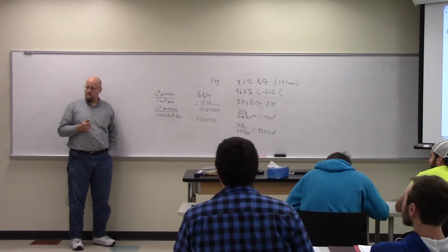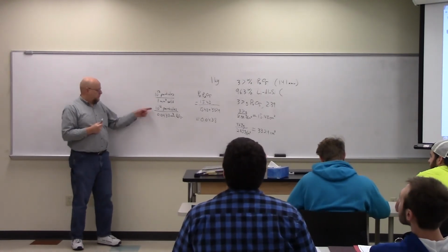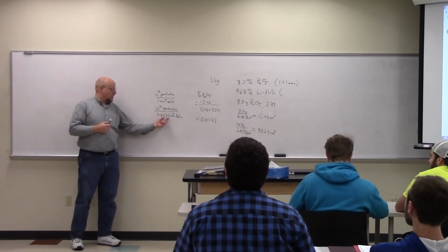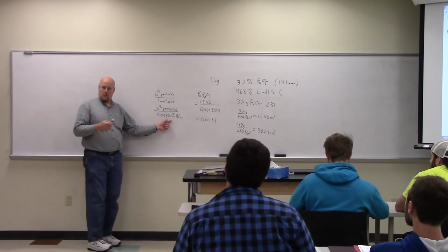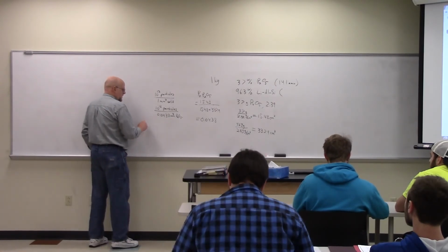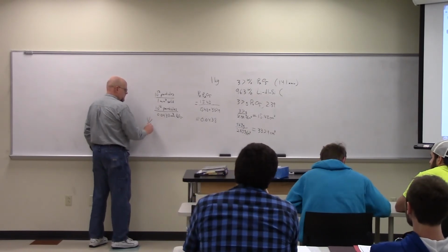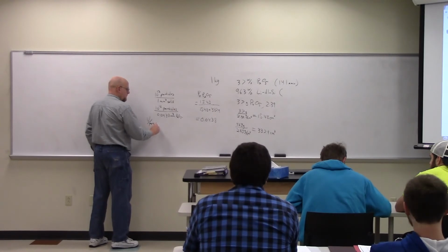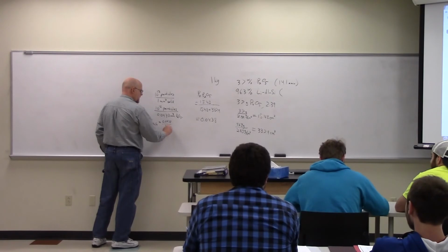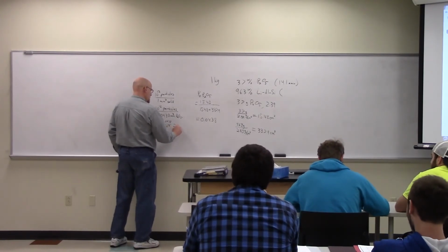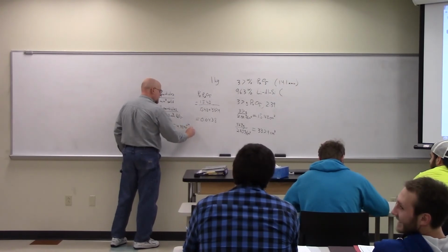That make sense? So that 10 to the 12 particles is distributed evenly among 0.0438 cubic millimeters of P2O5. Or the other way to look at it is that the volume of a particle is 0.0438 divided by 10 to the 12, or 4.38 times 10 to the minus 14 cubic millimeters.